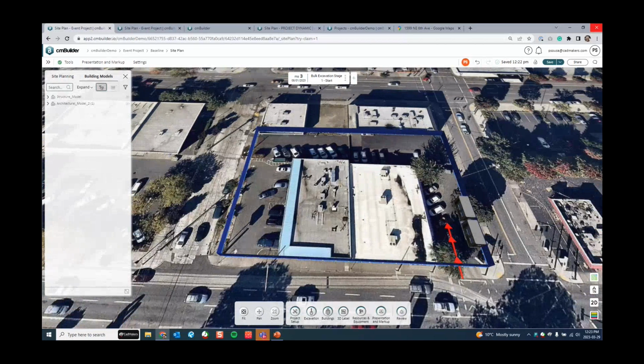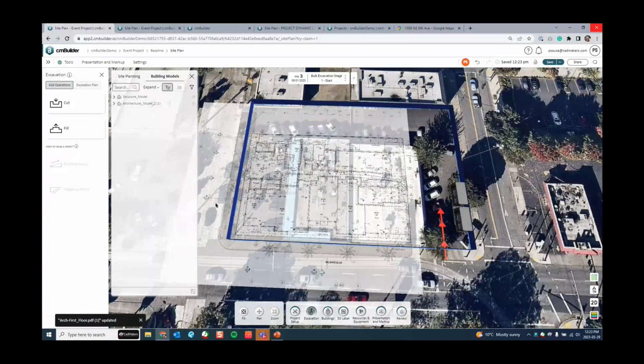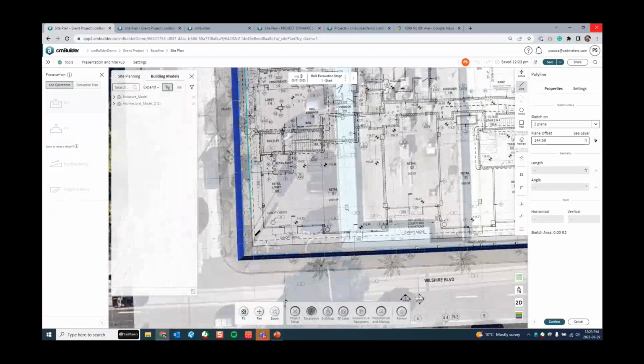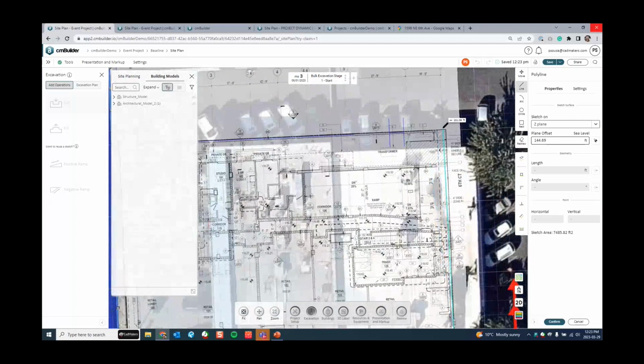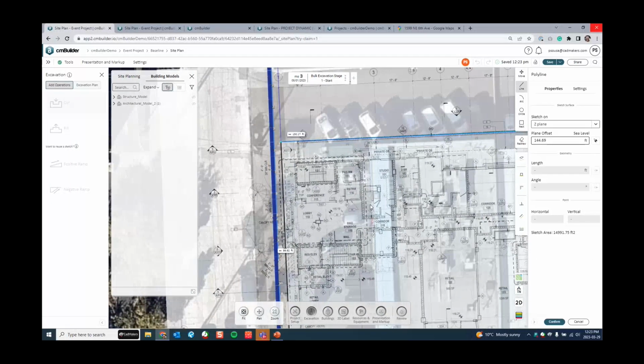And let's say that for my bulk excavation stage, the first one, I'm gonna actually use my drawing as my reference instead. And I'm gonna create one small excavation stage over here just to represent that this is the moment where I break ground, okay? So I'm gonna do a cleaning up of my site.